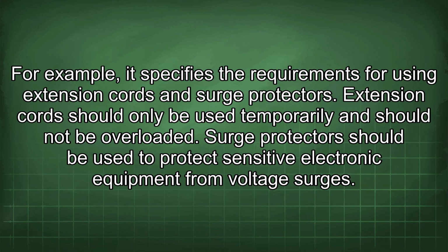The NEC also provides guidance on the proper use of electrical equipment. For example, it specifies the requirements for using extension cords and surge protectors. Extension cords should only be used temporarily and should not be overloaded. Surge protectors should be used to protect sensitive electronic equipment from voltage surges.